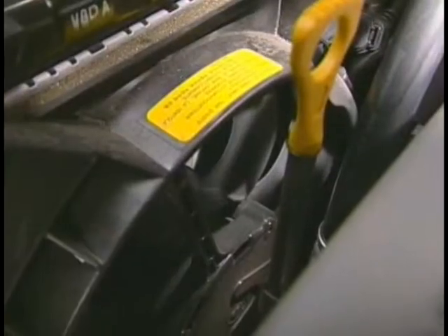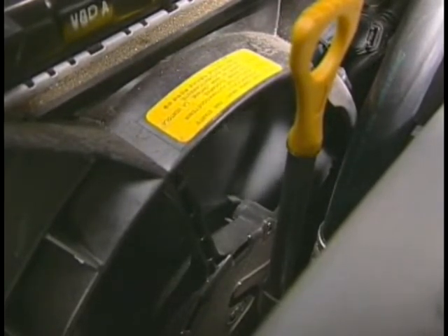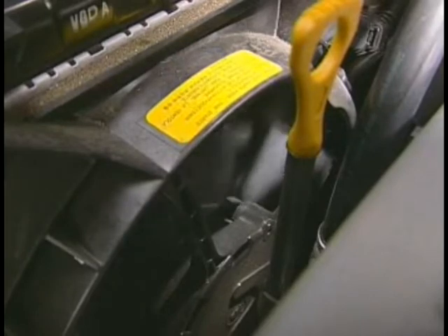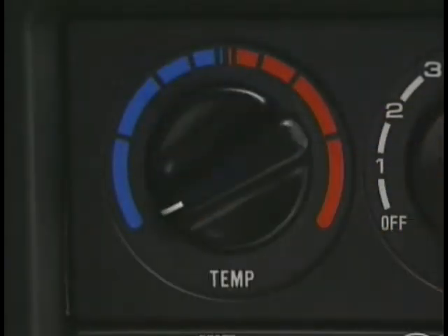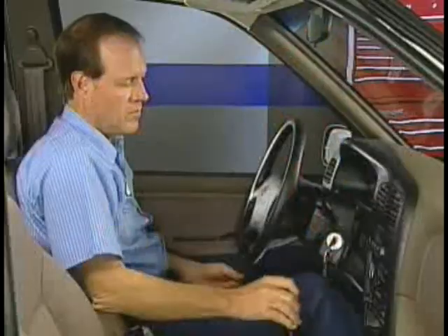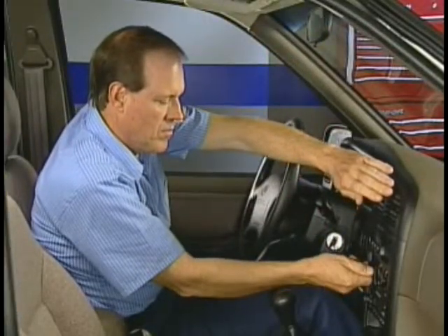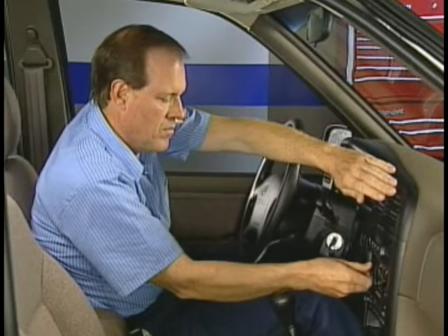If the vehicle is equipped with an electric condenser fan, listen also for the condenser fan turning on when the AC is turned on. An inoperative condenser fan will cause poor cooling in the condenser. Next, move the temperature control to full hot and then back again to full cold. The system should respond accordingly. If there is no change or the change is minimal, check the linkage, doors, and vacuum or electrical controls to determine where the problem exists.